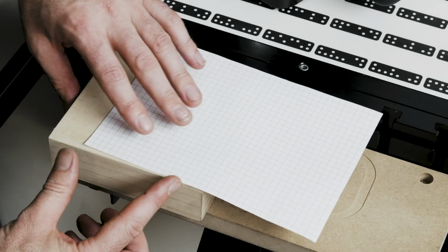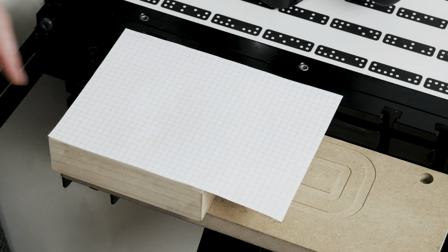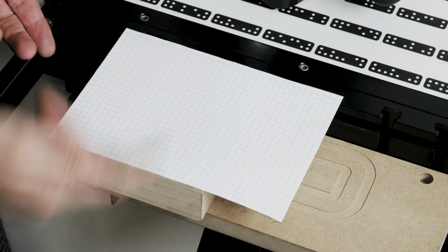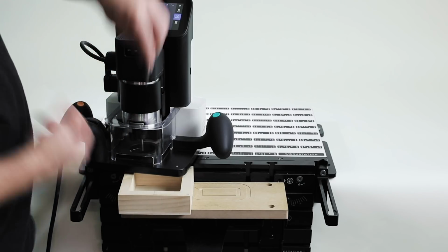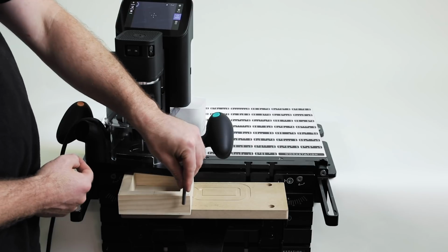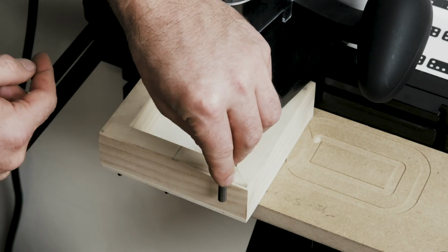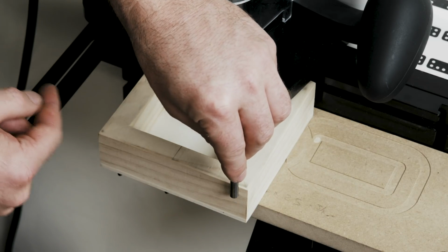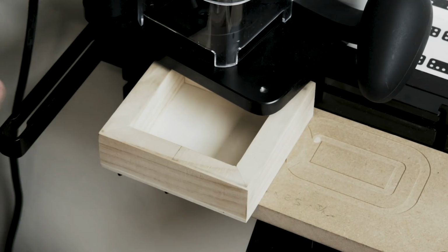Probe 1, probe 2, and then probe 3 for a perfectly aligned grid. That enables us to place things in the right orientation and specific increments from each edge very easily. To do that, we're going to take a cutter, insert it inside the spindle upside down, and use Origin's spindle mechanism and this perfectly round cylinder as a measuring device. We're going to drop it down below the surface and then bring it up and lightly touch it against the edge of this stock in two locations to get a straight line.